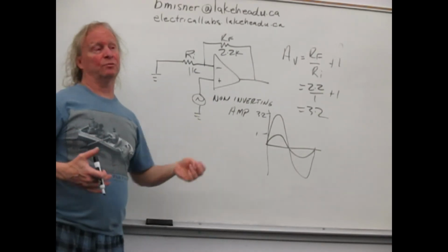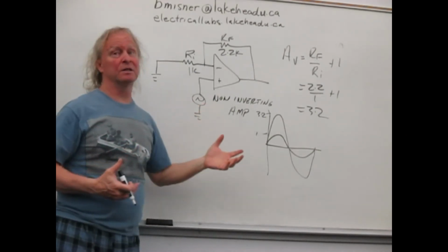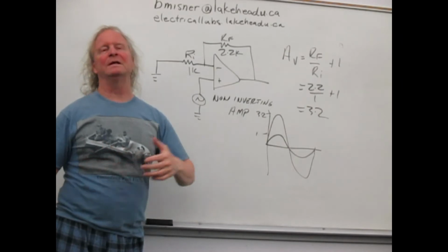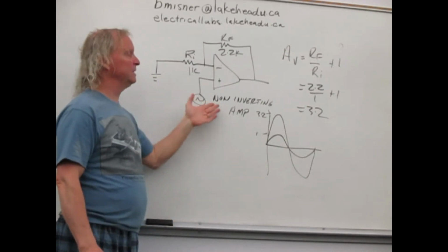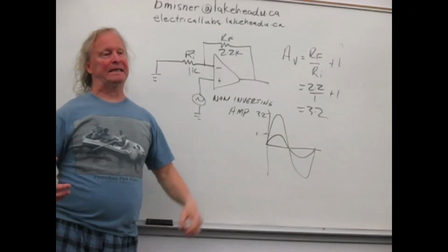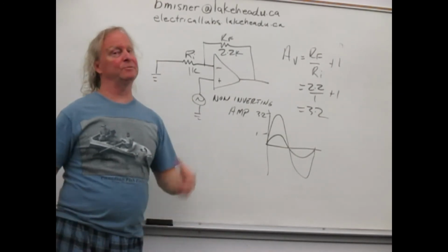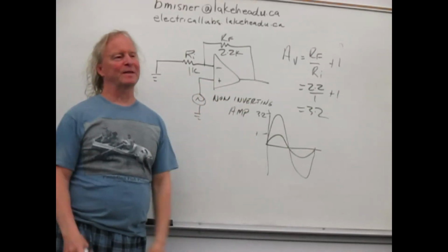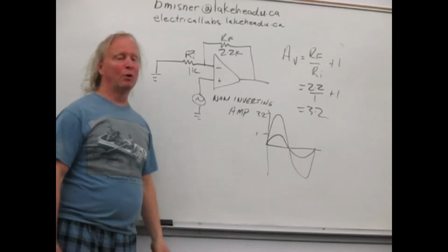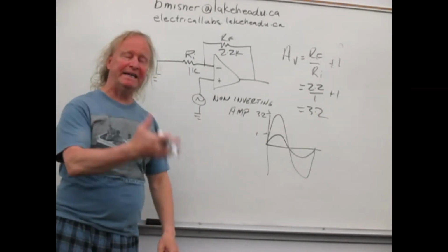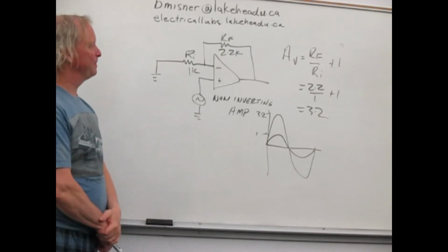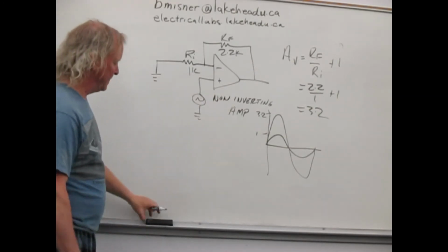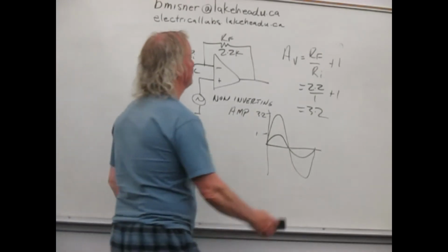A lot of times, most times, when I design these circuits, I always use the inverting amplifier. And then if I need it inverted back to normal, I do that. Because a lot of times, the non-inverting circuitry gets a lot more complicated. The inverting amplifiers keep it kind of simple. So most of our applications will be using an inverted input. But it is possible to make a non-inverting one. Okay, so that's our second circuit.